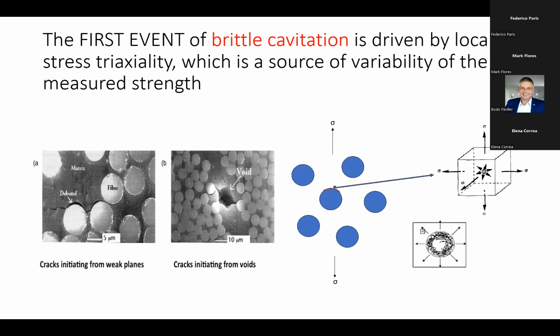That is cluster formation. If you look at the bottom left picture, when there are fiber clusters, the conditions are favorable for the brittle cavitation to occur and debonding to form. And because of the closeness of the fibers, multiple debonds will be able to link up easily.